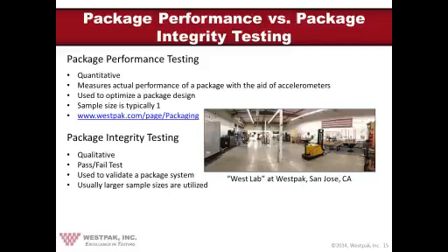Another important thing that this kind of test does for you is to give you a determination of headspace, or what people might call margin. Say the boss asks you, okay, so it's a good package design, huh? How much margin do I have? Well, if you did a performance test, you would know. Hey, boss, I've got 100%. You'd also know if you're overpackaged. And if you've got 100% margin, you're probably overpackaged. So you can do a lot of this kind of analysis once you do a performance test. You do have to know, however, the limits that the product can take, because the product and package work together as a system.